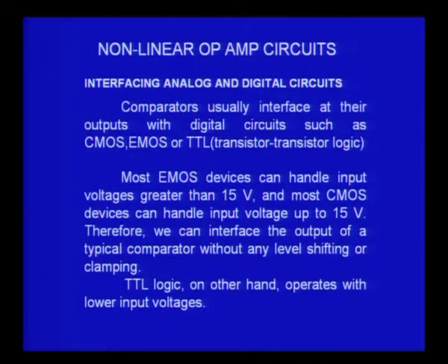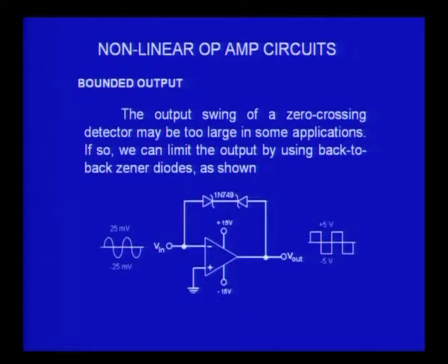For that, we can think of another application, and this is the circuit which I show now, where I have used in the feedback two diodes, two Zener diodes to be precise. For example, I have used 1N749, which has a breakdown voltage of about 4.3 volts, and they are connected in opposition. One is connected in this direction, the other in the opposite direction.